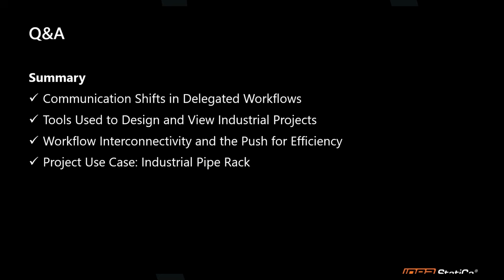I mean, it depends on the person. I always like to try to have a phone call initially and then follow that up with a more formal RFI. But sometimes the communication's not there, and an RFI becomes your only main option. There have been quite a few instances where you have to ask. I had a situation recently where they said that the connection must transfer the full plastic moments, and as soon as you did that, it made the columns fail, and that obviously wasn't what their analysis showed and what was really occurring. So I had to reach out and ask an RFI for the actual design loads, and when doing that I saw a drastic reduction from plastic.